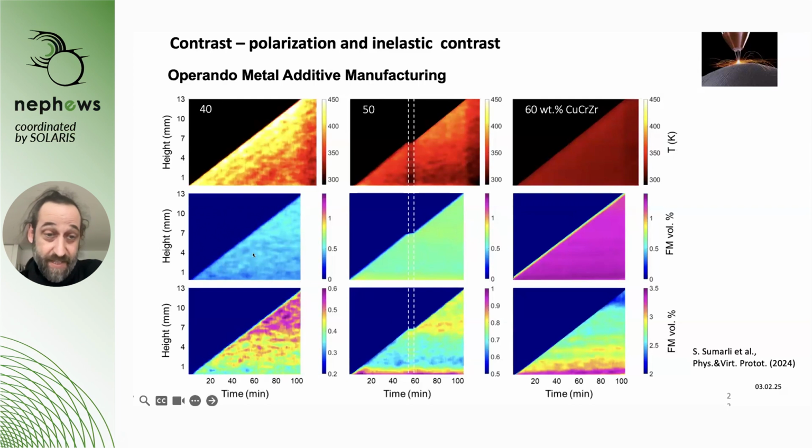of the ferritic phase content, which you see in this row, and you see that we get more ferrite the more copper we have in the sample. But then we can also look into detail when we now have a scale, a logarithmic scale, which is adapted to the amount of ferrite in the sample.